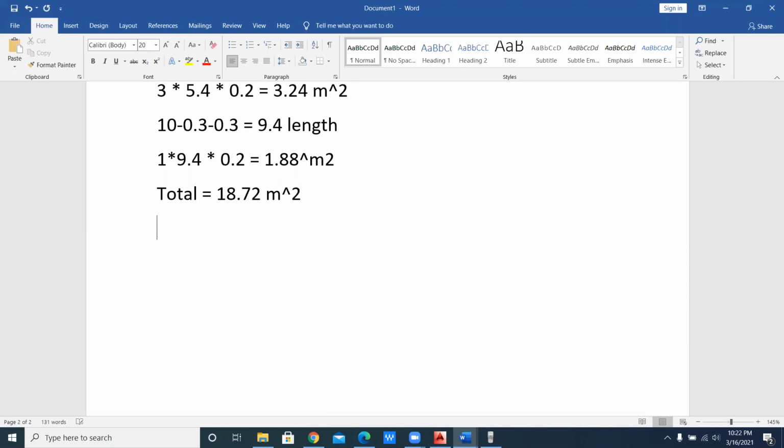Now I'm going to take the other, that is the beam in y direction. You have to take the dimension of the slab from the center of the grid, that is from the center of the column, because your slab is normally placed into the center of the grid. Now the other thing that we normally take is the beam in y direction.